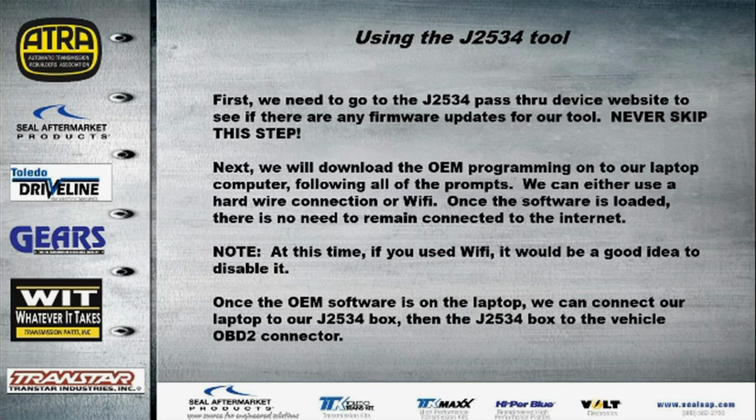So again, we get that loaded onto our laptop, and at this point, a very important note, you don't even want to be connected to the vehicle. At this point we're just accessing the OEM with our laptop directly through the internet. We're not connected to the vehicle, because in some vehicle programming applications, we have to connect all the way through from the internet straight to the vehicle.